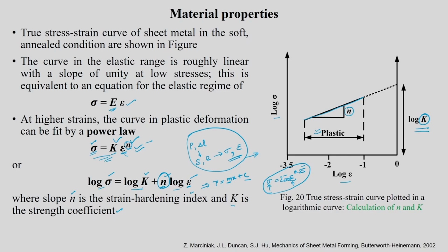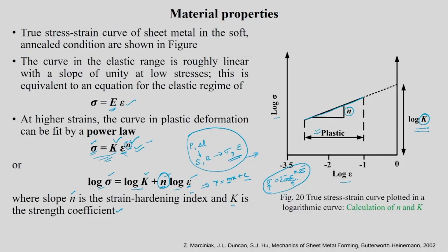So, in that region of deformation, where you do not have data, what you can do is extrapolate this equation and use it to relate sigma and epsilon beyond the tensile test also. Otherwise, you do not know how to extend it beyond your true stress strain data from experiments. If you want to extrapolate it, you need some form of equation, and this fit equation will give you that in the extrapolated region.